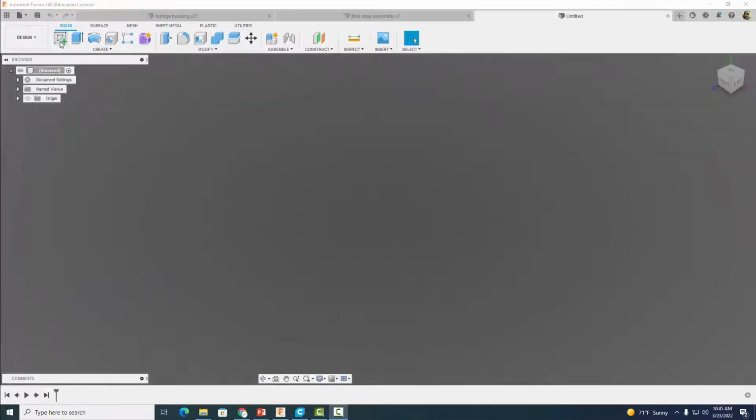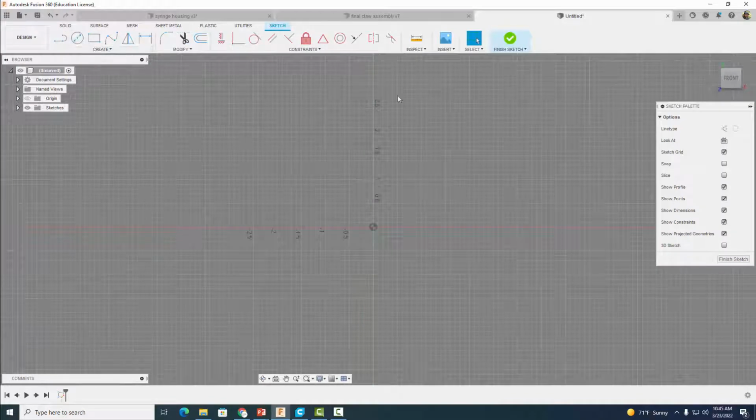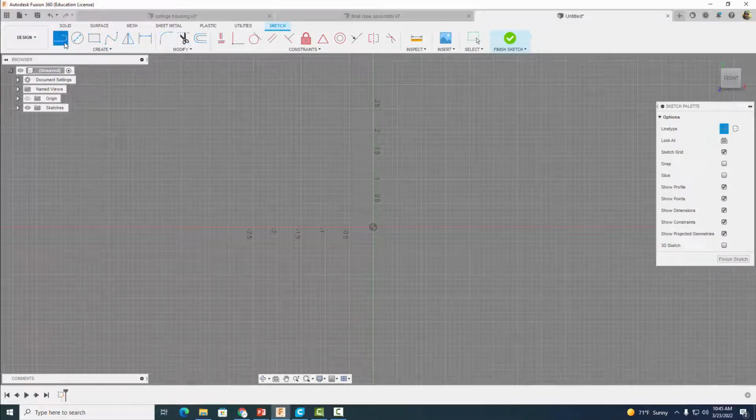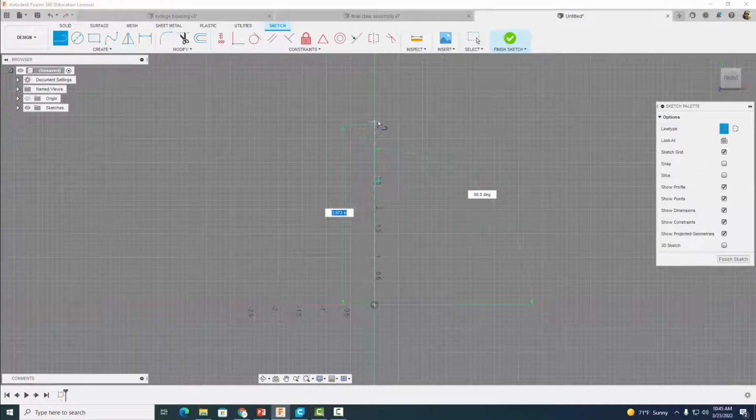All right, so the first thing I'm gonna do is start a sketch here on my XY plane. And I'm gonna create a construction line that goes right down the middle, and this represents the center axis of our syringe housing. So it's kind of like a line going right down the center of the tube. Okay, and I'm just going to make it 4 inches or so. I'm going to hit escape, take it out of construction line, because I always forget.